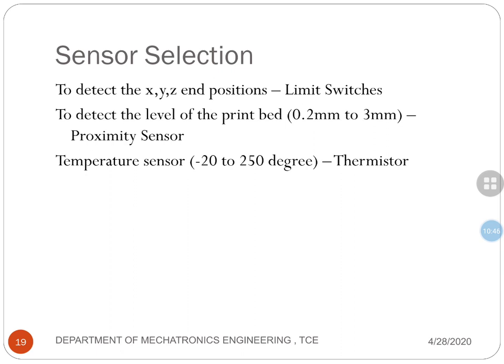This is the sensor selection step. Sensor selection depends on the operating range, the bandwidth, the power supply of the sensor, the operating frequency, and the payload.